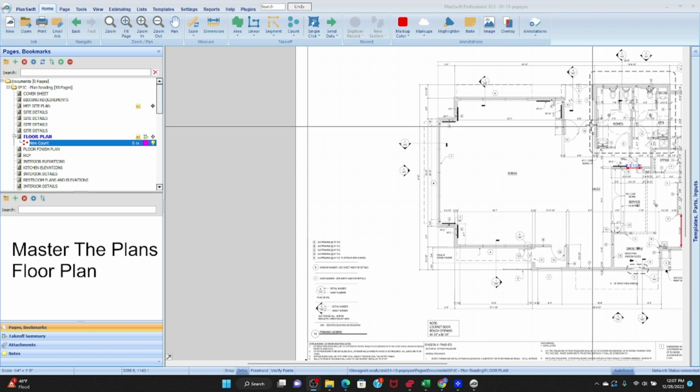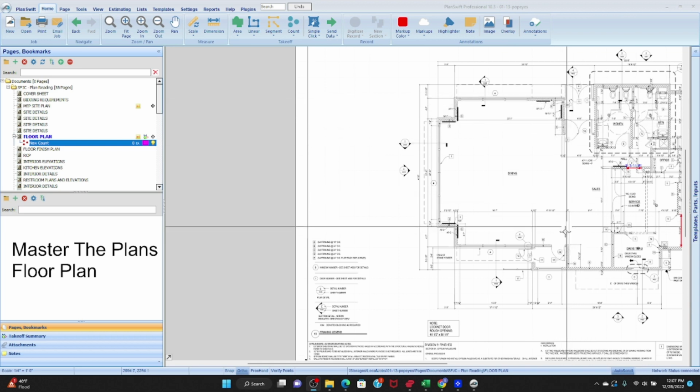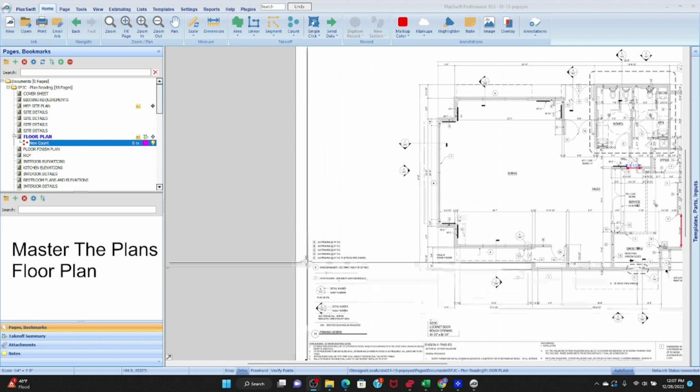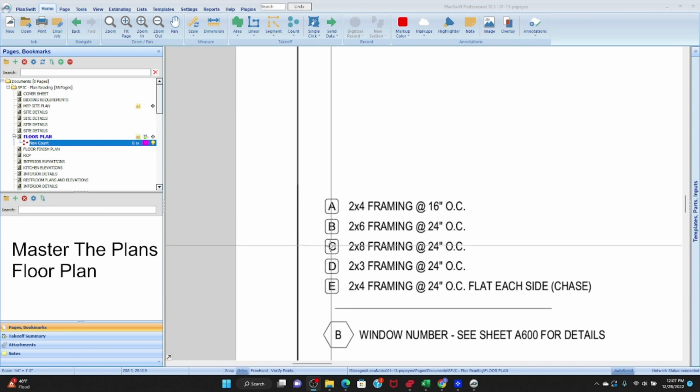Okay, and now the only thing left to do is to just determine how many linear feet, right, of each type of wall. Okay, the purpose of the floor plan is to identify the types of walls, identify what we're making them out of, and then use that plan to measure what? How many linear feet? We cannot use the floor plan to determine the height of the wall.